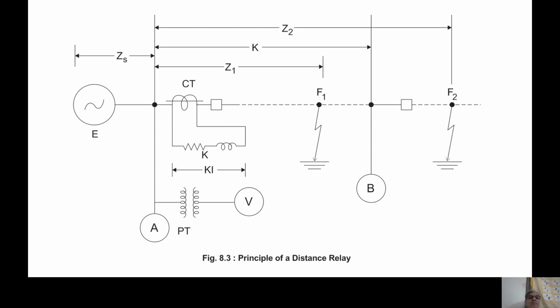I have got some relay R. CT is there, right? Line AB is there. I want to protect line AB. And the impedance of line AB is known well before even erecting the line, because I knew what is going to be the distance between R and Y wire, Y and B wire.